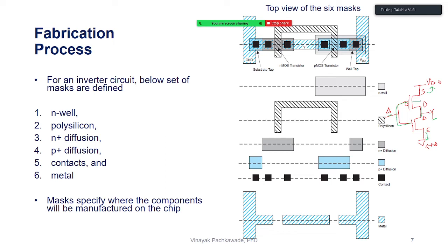And the body of PMOS I show with the schematic. If I want to show it through a schematic diagram, I would say the body of PMOS, which is N-well, I show it this way. It is tied to VDD, or I would say it is tied to the source, and ultimately the source is tied to VDD. Here the body of NMOS is tied to ground, or it is tied to the source, and the source is ultimately tied to ground. So this is how I represent it.